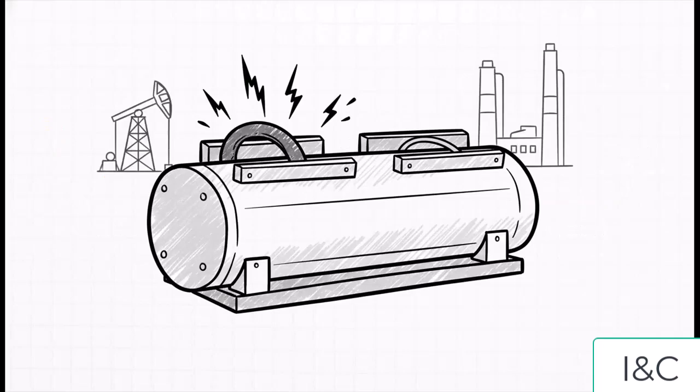And hey, for all of you working in refineries, petrochemical plants, this next one's for you. API RP 552 is your rulebook. It was written specifically for these tough, electrically noisy places. It flat out mandates that you separate instrument cables from electrical cables, especially around things like compressor skids, where EMI is just a massive problem.